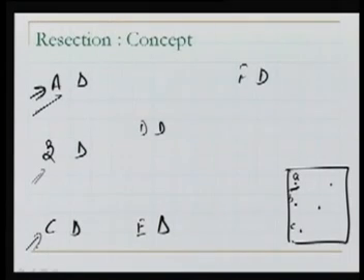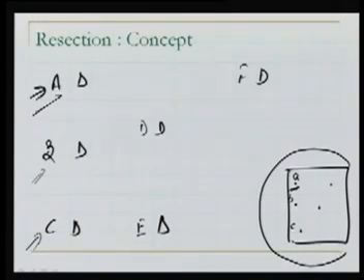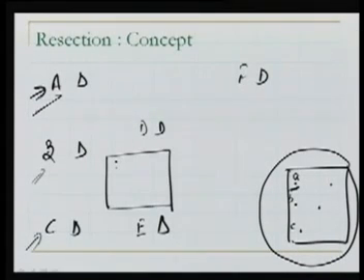Now when we take this plane table to the field in order to plot the details, for example, let us say I'm occupying somewhere here, and I've got these stations plotted. In order to start plotting, as we have seen in the method of radiation, let us say we want to do the method of radiation. In order to start plotting, what should I do? Number one, I must orient my table. If my table is not oriented, I cannot plot, and if I plot, my map will be distorted.